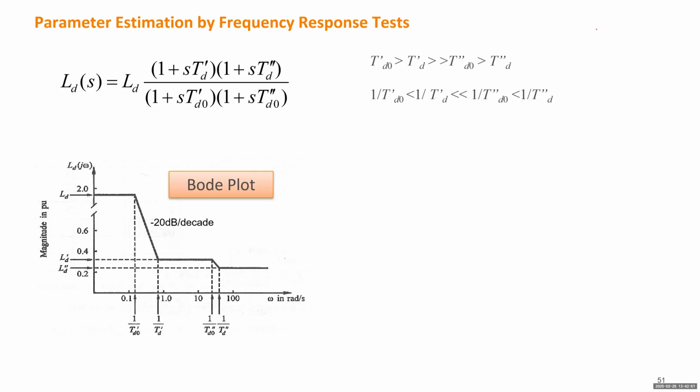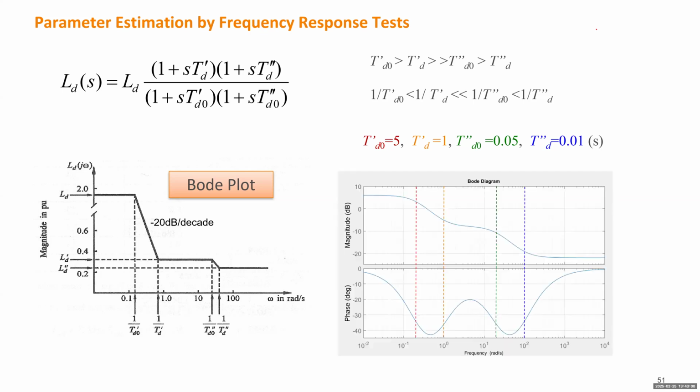So you can utilize those phase plots to help you identify where the real turning point is. Let's assume some typical values. Here you can use MATLAB to draw the Bode diagram. This is a magnitude diagram. This is a phase diagram. The magnitude diagram does not come from 0 and suddenly change to -20, but it will go through some process. You have to somehow pick a point at the center, or you can have another way to do it.